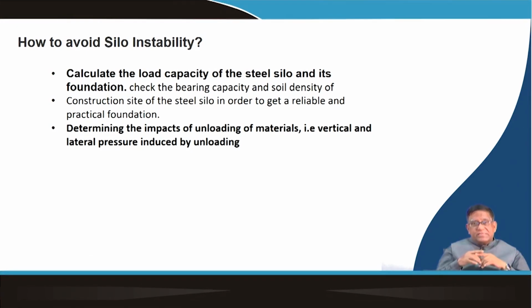We have discussed that in designing the silo, at which stage you should give the opening diameter, and what diameter should be taken. This is basically related to the distribution of shear strength and pressure. Now, if that distribution becomes improper because the material which is coming is different, then your silo will be subjected to failure.